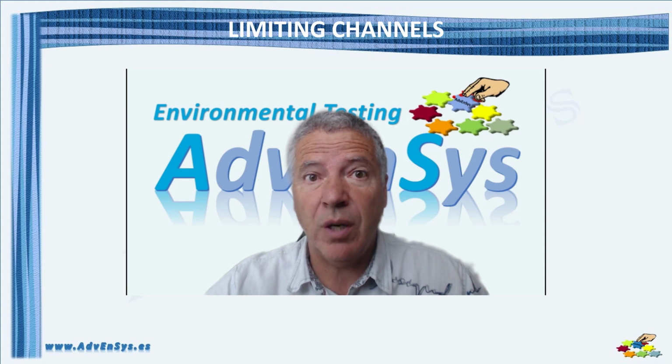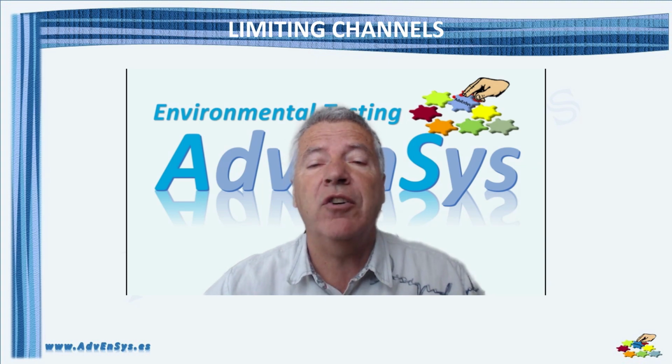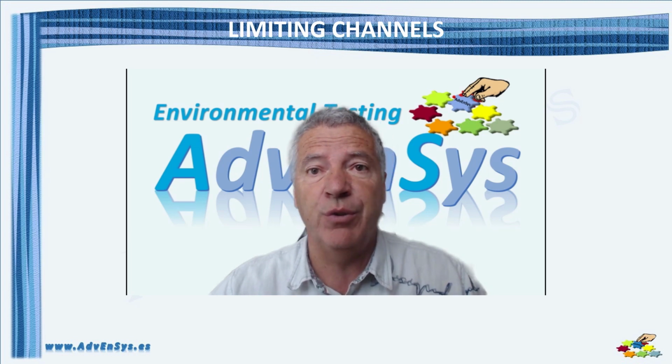Today, we are going to talk about limiting channels and different interesting uses we can give them in our vibration test. In a vibration test, we need to place one or several accelerometers to control the excitation level and one or more accelerometers to monitor the response of our DUT.